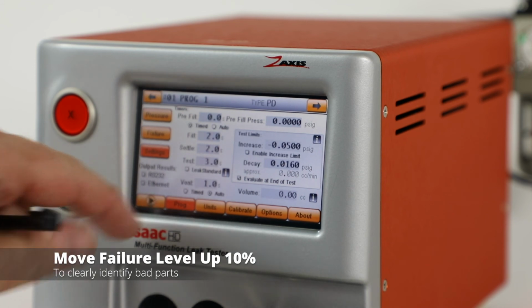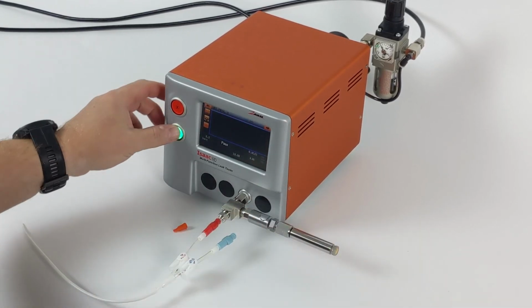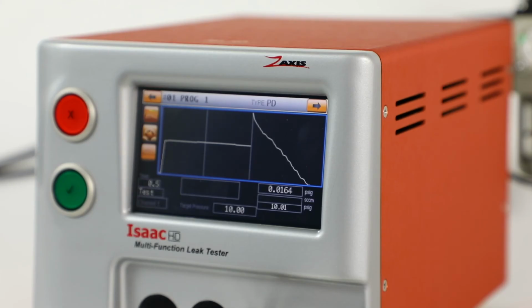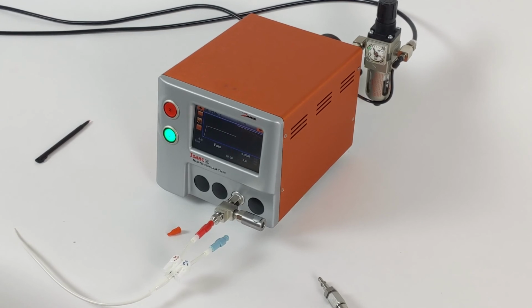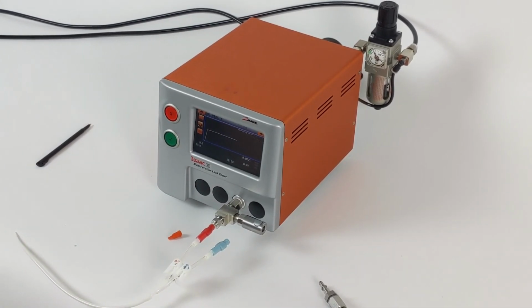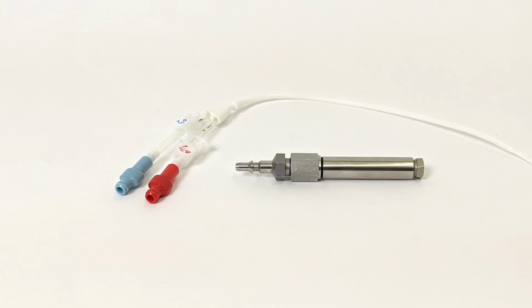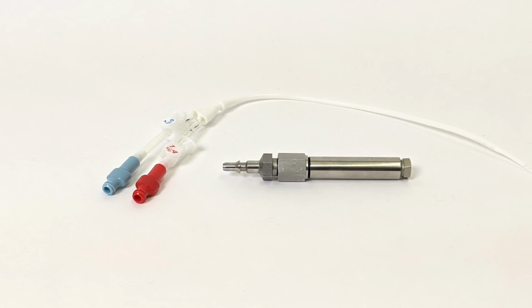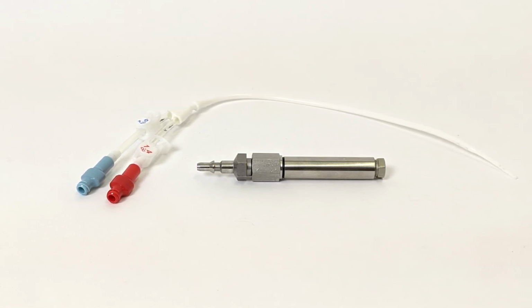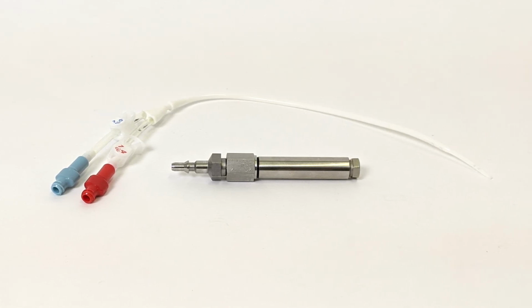So we can go out and prove that by running a test. We still have our 2-second fill, 2-second settle, and a 3-second test. We get a failure because we have more decay. So running the same part, this being a known good part, easily achievable that it's a good part. This can also be done if you had a device that leaks versus having an actual standard. You could make a device that has the manufacturing defect that you're looking for. Will allow us to do the same thing we've just done with the leak standard.